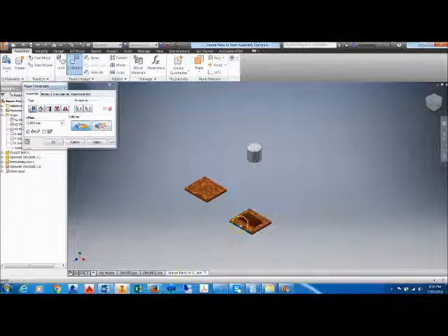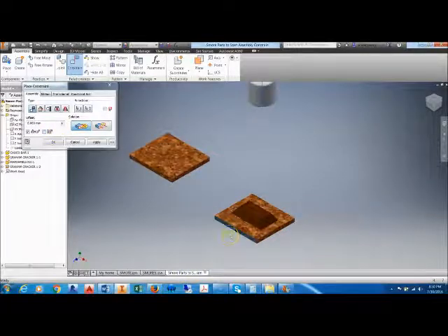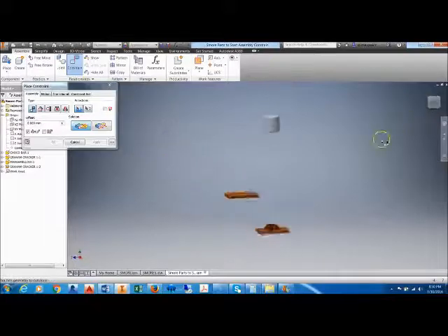Back to the assembly, and I'm going to utilize a negative number because I want to push away from my arrow, and I will use negative 28.5. And what I have done by hitting apply is I've now taken and pushed my marshmallow, you can see the axis, to the center of my assembly.